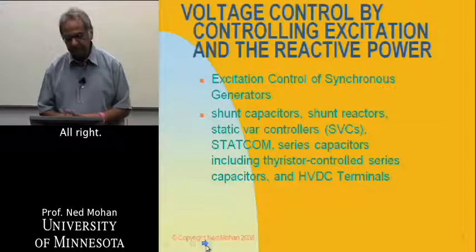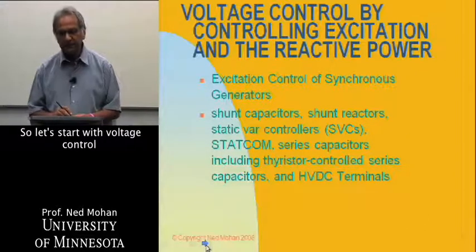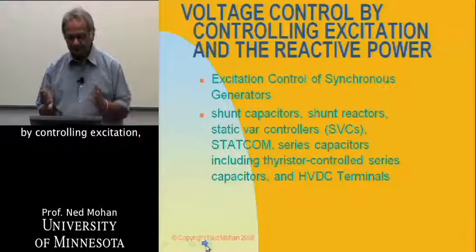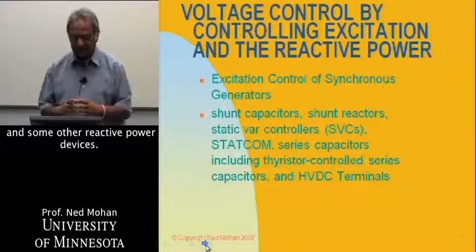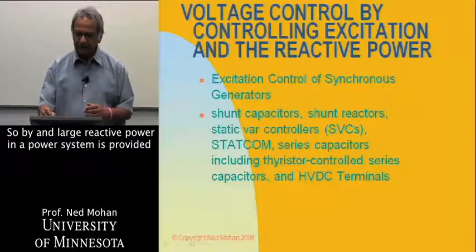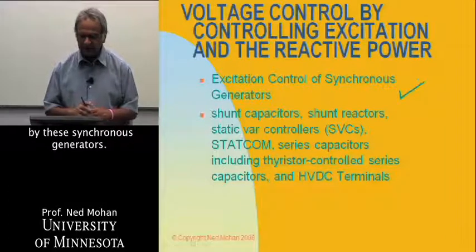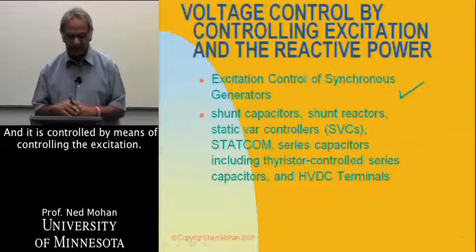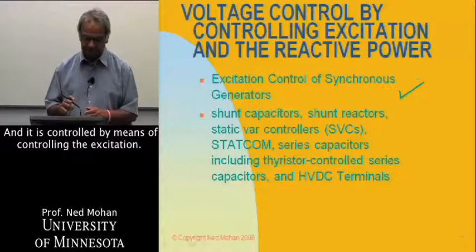All right, so let's start with voltage control by controlling excitation and some other reactive power devices. By and large, the reactive power in a power system is provided by synchronous generators, and it is controlled by means of controlling their excitation.